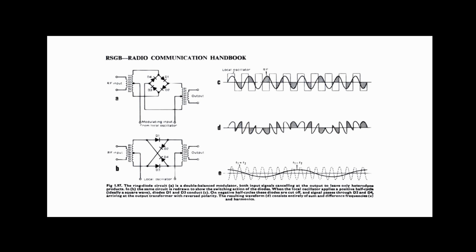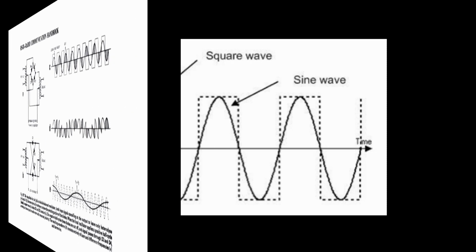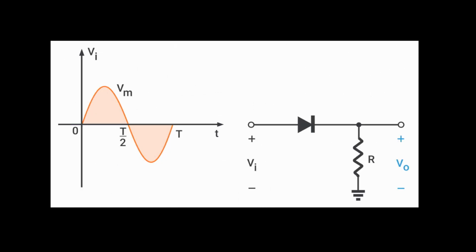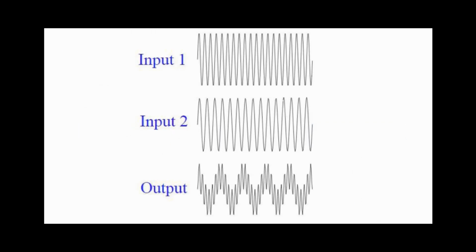So the next question: does a sine wave represent the best way to turn diodes on and off rapidly? Let's take a look at a sine wave. Some amount of current must flow to get the diodes through their turn-on curve and into saturation. The sine wave takes some time to get there. It's kind of an area under the curve issue and a rise time issue.